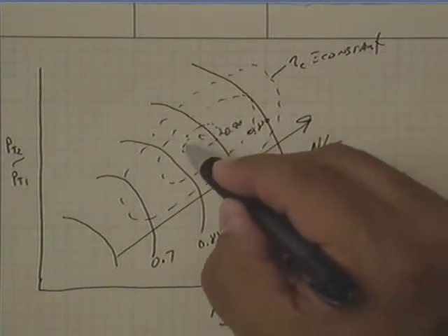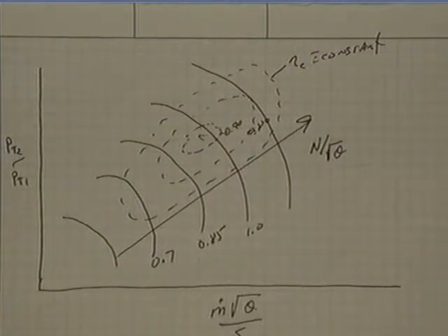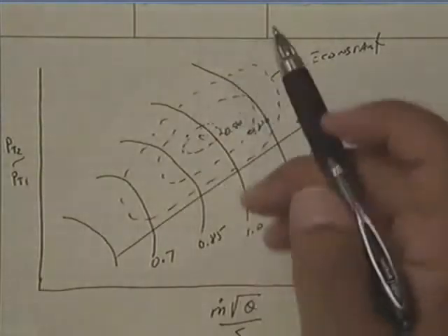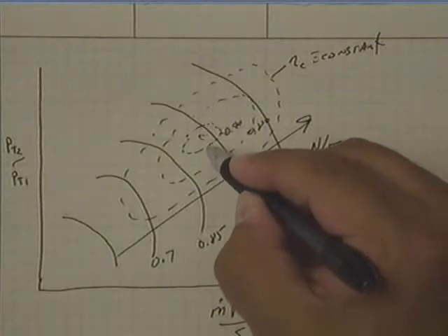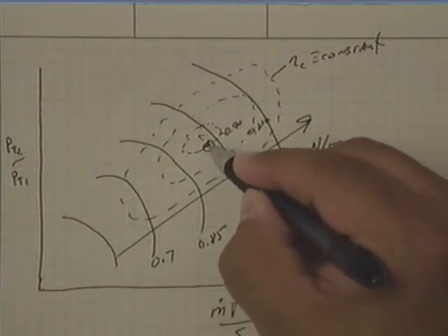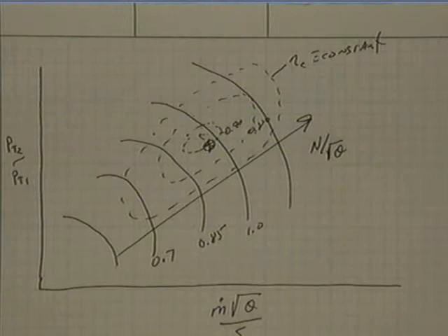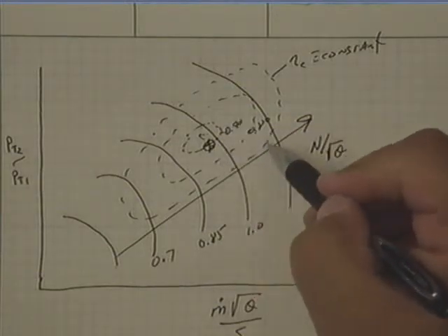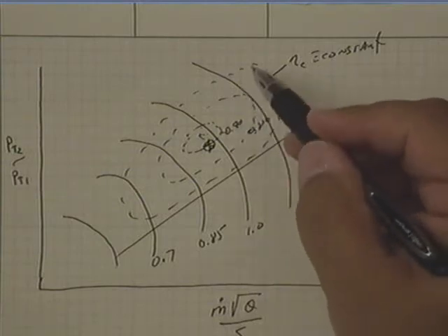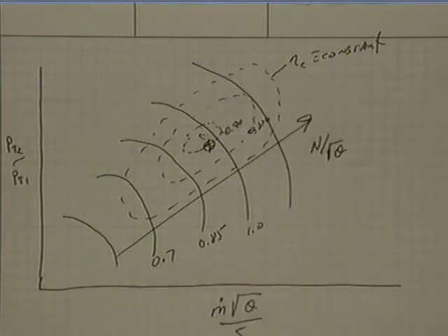So for each compressor, if you built a 10-stage axial flow compressor or a single-stage axial flow compressor, you can build this map, and it's actually done, right? You create these family curves, and this is where you would end up picking your design point. Okay, I want to operate here for cruise maybe, and then you can place yourself off design for where you would be for takeoff or climb, for all those other cases.